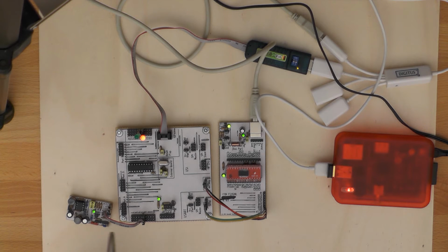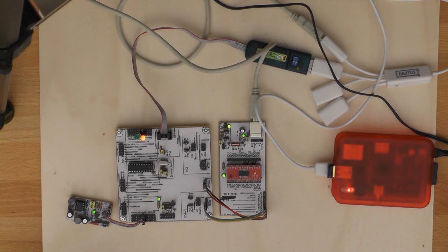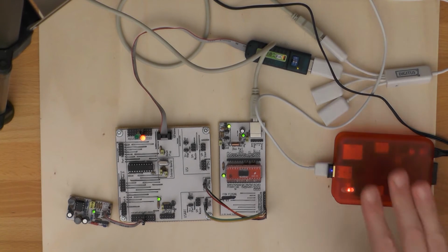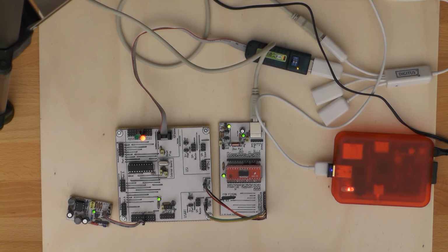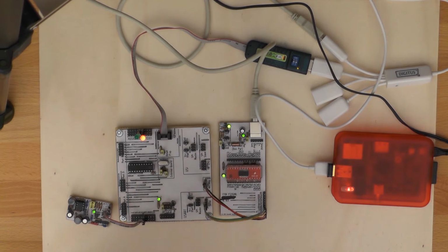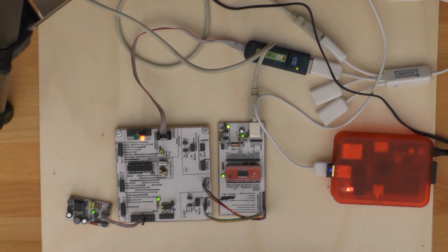From there, it goes on to a microcontroller. This is just some homemade test evaluation board. This is an Atmel ATtiny2313, which is probably the best choice for this sort of stuff, unless I have a way to connect this right away to a computer like a Raspberry Pi, which has an SPI interface, so I can avoid going through a serial interface, which then goes into an FT230 serial to USB adapter, which then connects to pretty much any computer.